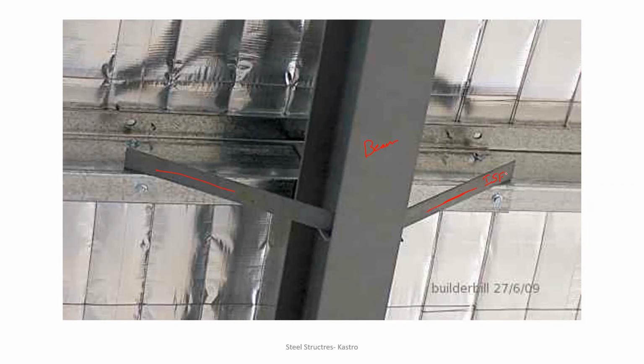If you provide certain kinds of lateral supports, they can be in the form of flats, angular sections, or channel sections. But most of the time we provide lateral supports in the form of flats. By the provision of the lateral support, you don't find any kind of deflection or twisting in the member. So this is one of the real-time examples of provision of the lateral supports.